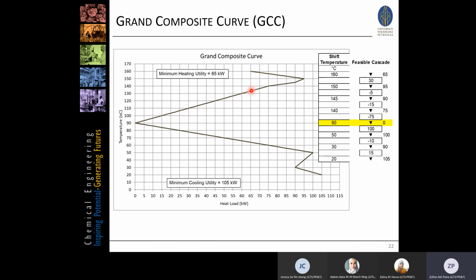So if the maximum is about 135 degrees C, and we have a 5-bar steam somewhere, which is 150 degrees C, we can just better use it, right? In this case, we could also use a 4-bar steam, sorry, it's about 140 degrees C. So it's somewhere here. That means we can use 4-bar steam. We can use 5-bar steam. We could also use 20-bar steam, somewhere here, or 40-bar steam.